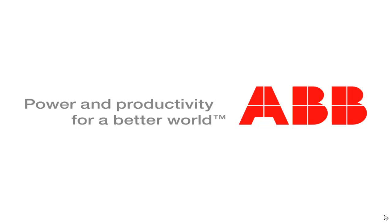But in terms of industrial water treatment, the system is at ambient temperature, so we don't bother with it. What about when you try to minimize or reduce sludge production? Again, temperature doesn't really play a part for our system. pH plays a part, and also the coagulant dose. But primarily, we've managed to reduce sludge production through the downstream processes that we managed to optimize before it gets to the settlement tanks.